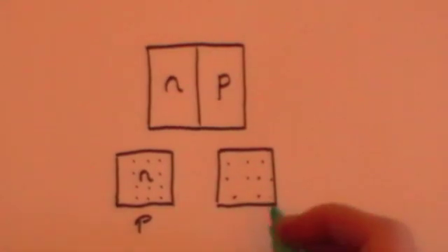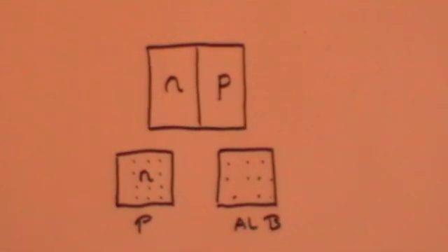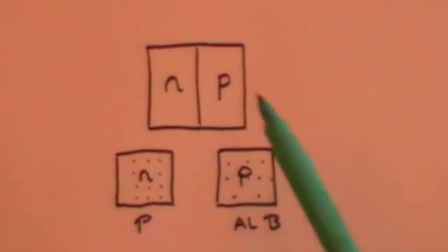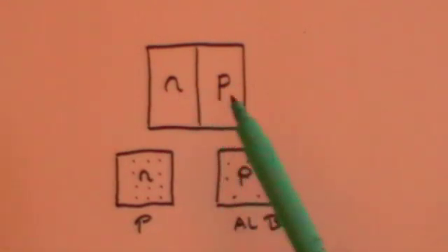Or you can dope the material with something like aluminium or boron. The point about these is they have one fewer electron in the outer shell than silicon does. So there is a deficit of electrons in this material compared with what it would have been if you hadn't doped it. And therefore it has a net positive flavour because it's got a deficit of negative charge. So you could say that's a positive charge. So you've got N-type and P-type material, which are both silicon but doped with different materials. And then I said you just bring them together so they physically touch one another.